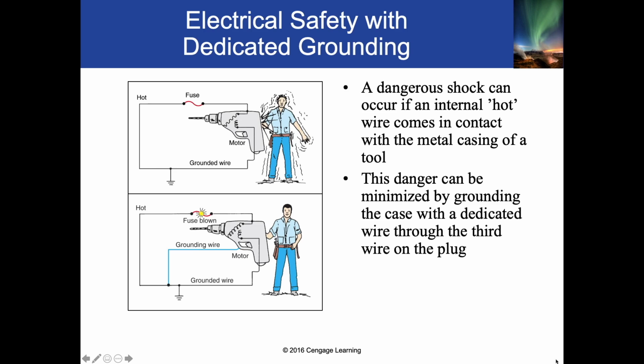Oh, sorry, it's coming out of the black side and going to the red side and going around in this circle. So none of that actually is grounded, right? There's a closed circuit, but nothing is touching the ground. So when you add a third wire to the system and have it actually touching the ground, that's how you prevent yourself from getting electrocuted.